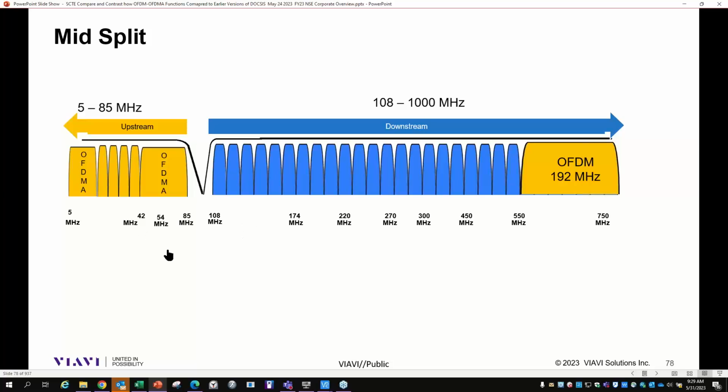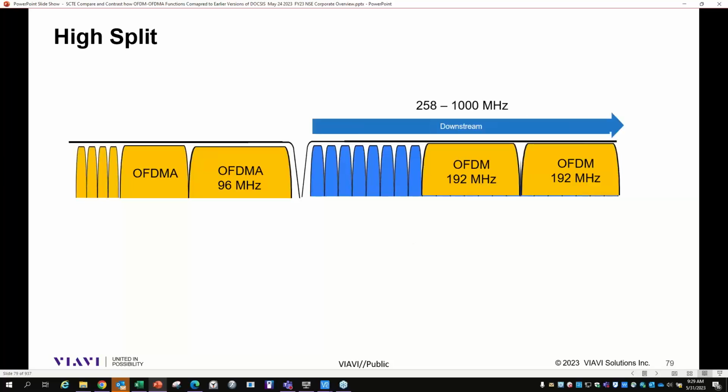So the variations are different, all right, but the expansion of bandwidth is still the same thing for the downstream, maybe 108 megahertz to 1 gig. You still got obviously your digital video carriers and also your DOCSIS 3.1 and 1 OFDM carrier, for example. So they vary. So this is the next kind of generation of where systems are looking to move forward, right?